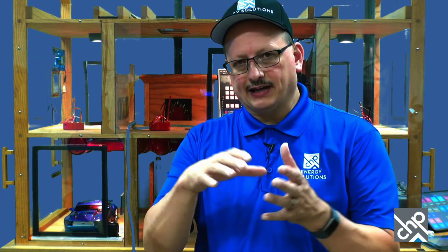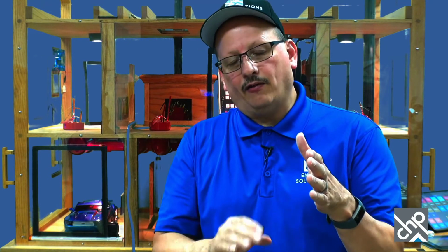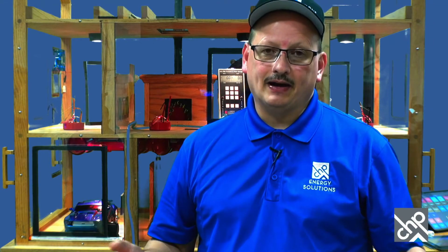What happened was, underneath, it didn't get installed very well, and there's like a 10 or 12-inch duct, and part of it was not connected. It had fallen down. I actually ended up doing a duct test later, and it came up about 350 CFM of leakage. Essentially, what was going on was it was depressurizing the house. It was pulling in hot, humid air. In this particular home, they kept it relatively cold, like 70 degrees or less. And so when that warm, moist air came in, it was condensing.